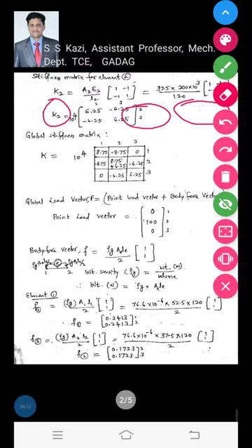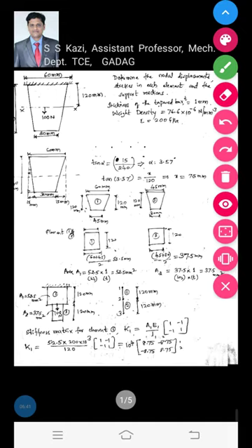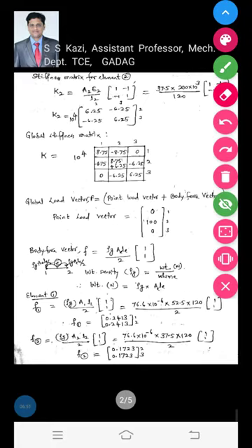Here you can observe, first we will write the point load vector, just the point load values. For node 1 it is 0, as at node 1 there is no applied force. Next, at node 2 I wrote plus 100, because the load acting at node 2 is 100, and the direction of this load is the same as the direction of element numbering, hence I wrote positive. Now next, at node 3 the point load is 0, there is no applied force at node 3.